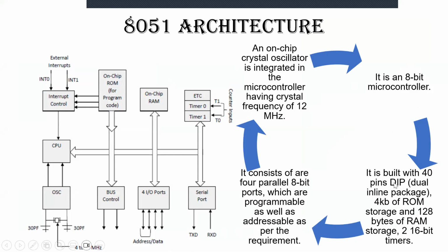It has 40 pins, which are in a dual in-line package. The memory storage is 4 KB of ROM and 128 bytes of RAM. So these are the memory storages, and you have timers which are 16-bit.